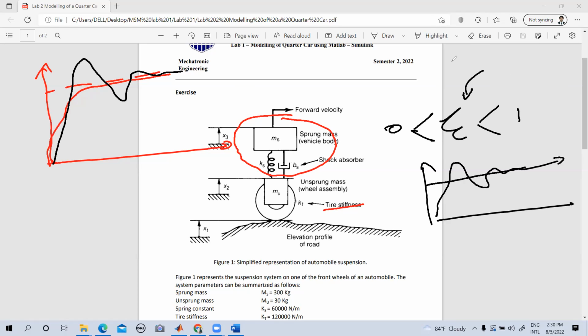So you increase the damping coefficient? Yeah, correct. So that's actually the understanding you should have, right? If you get a response like this, that means it's sort of underdamped, right? The name itself suggests that. So it's like the spring constant. Either you have to reduce the spring constant, or you have to increase the damping coefficient, right?